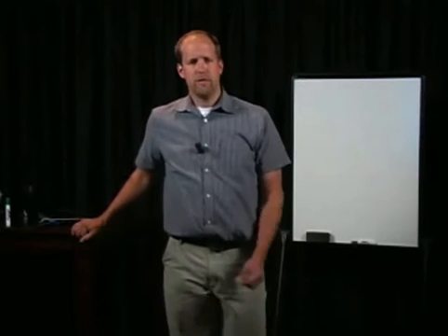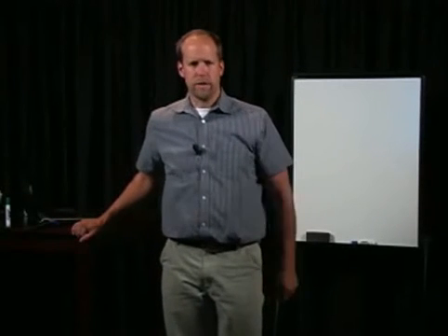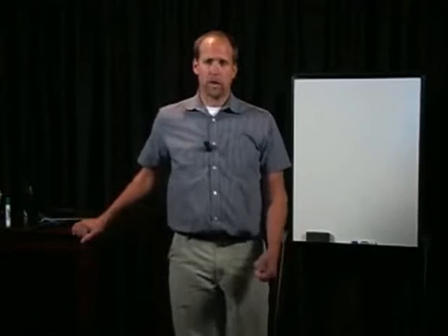Protective clothing is recommended for underfloor crawl spaces and attic spaces and some other areas that you may be involved with during a building inspection. Protective clothing is recommended for medium and large remediation jobs for sure. Protective clothing prevents the transfer and spread of mold to other clothing and eliminates skin contact with mold, which is really essential to understand when you're doing an underfloor crawl space inspection and remediation work.